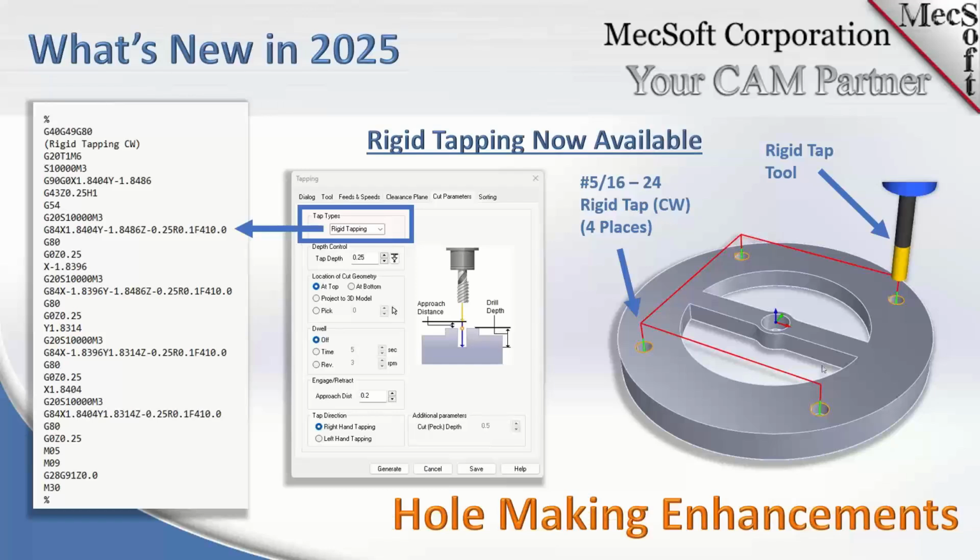But there's one thing you need to know about this. The rigid tapping is a lot more accurate. But there is one thing you want to be concerned about. Because it's rigid, you want to make sure you have your parameters correct, because it puts more stress on the tap tool itself. Joe, do you want to add any more to that? I know it was kind of awkward explanations. I think it's too difficult to explain with words, so you need pictures.